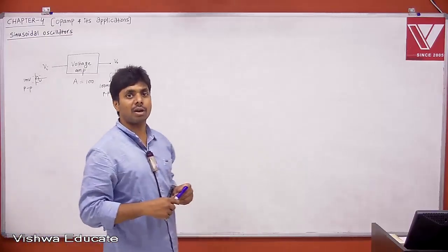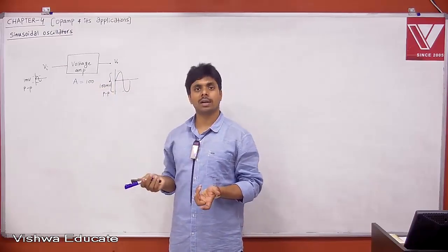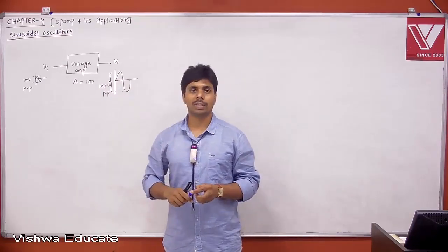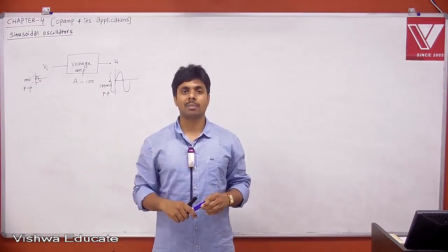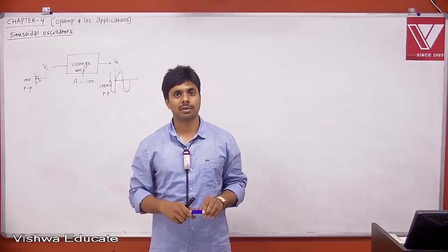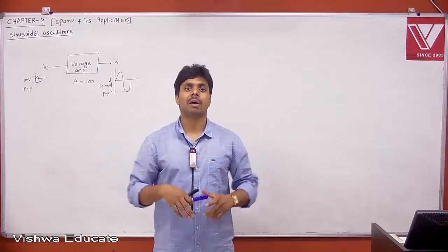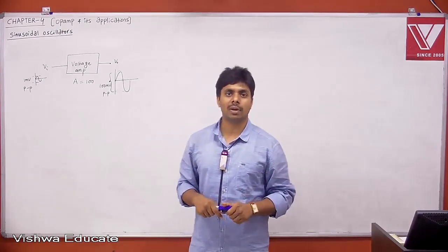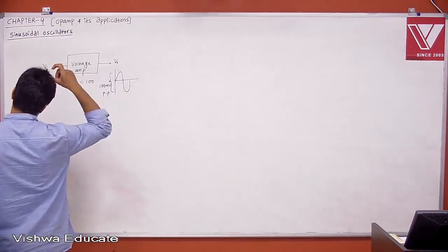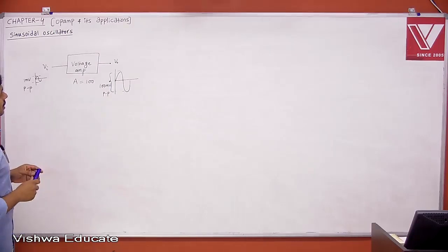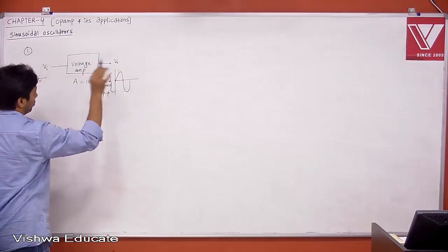I already explained the step-up transformer. If N2 by N1 is equal to 100, a step-up transformer also gives you voltage amplification, but it does not have power gain. Without power gain, whatever voltage or current amplification you have is not considered an amplifier. Without power gain, it is not called a voltage amplifier, current amplifier, transconductance amplifier or transresistance amplifier. I already explained that; we invested more time there. That's fine. Similarly, this is one, the voltage amplifier: voltage as input, voltage as output.